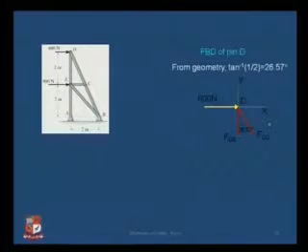Now drawing an FBD at point D, I am getting this, that is I have a 600 Newton force horizontal. Then I have a member DC which is at 26.57 degrees. How do I get that? By finding out the angles with respect to this length. Because this is 2 meter, this length automatically becomes 1 meter, and this height is 2 meter, from which I have found out this angle, 26.57 degree. Another force which is being applied is force FDE.